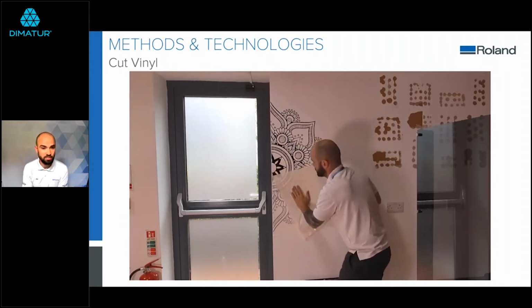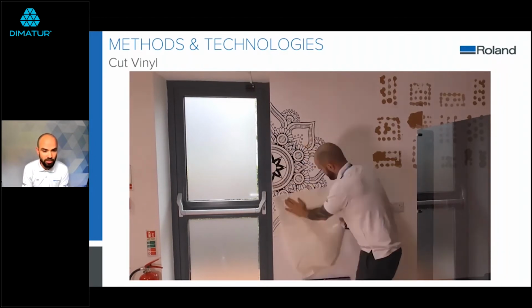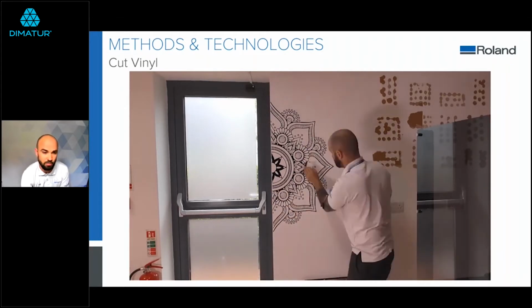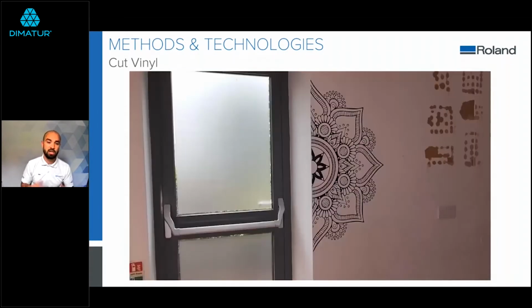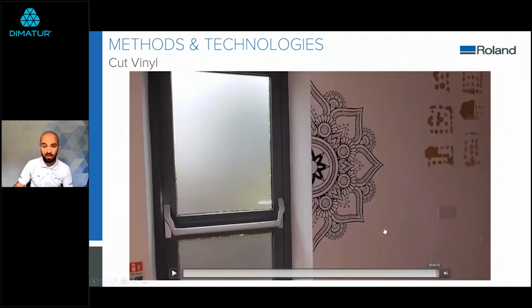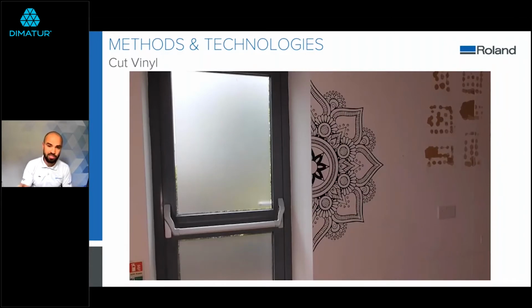This bit of wall there, I think, is either plasterboard or it might have been some wood, some sort of painted wood finish. And obviously you do need to check that you're going to prep the wall first. So normally this would involve a lot of cleaning of the wall, just to check that it's all nice and clean and that your vinyl is going to stick properly. Cleaning is a very important part of doing your wall graphics. This was a painted wall that was painted a long time ago, so there were no issues with waiting for the paint to cure or outgas properly.